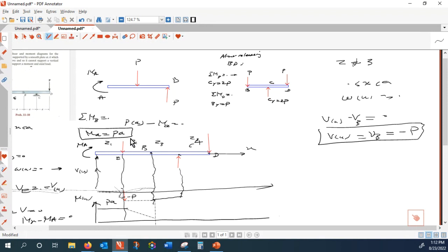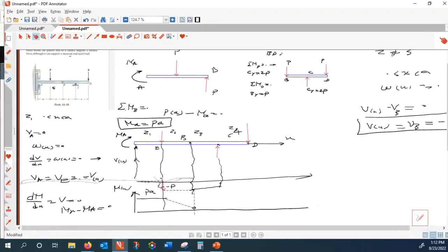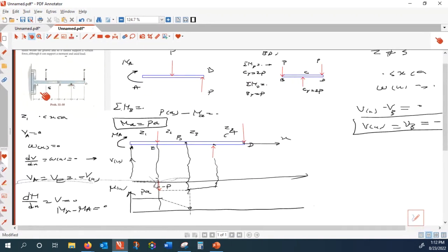Right? So it keeps going here. And then just look at this. We found M of B equal to 0. Does it comply with the physical limitation of the beam? The physical limitation of the beam is at point B, you have a hinge, it cannot take a bending moment. So at point B, you expect to have 0 bending moment, and now this is 0. That fits the expectation.